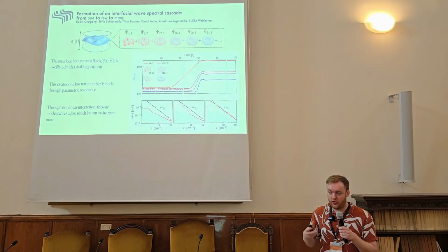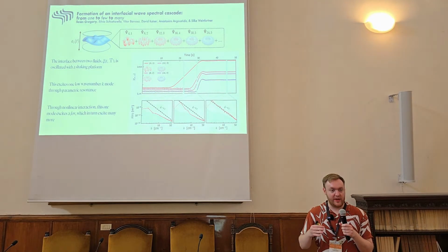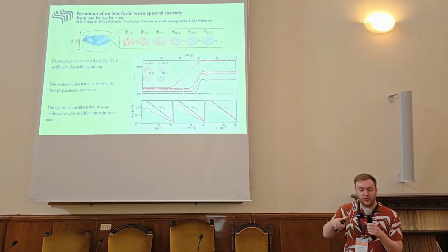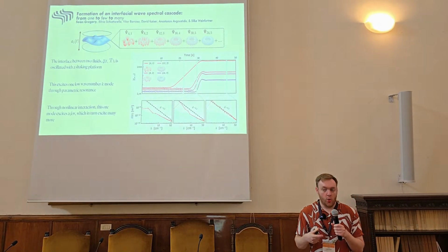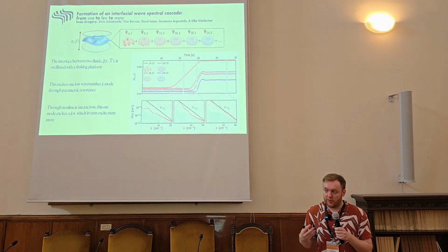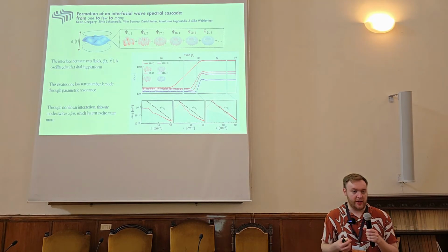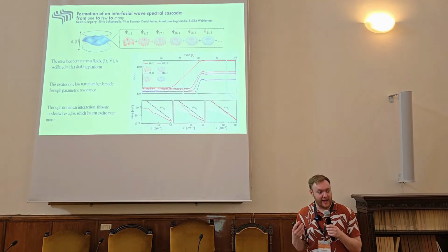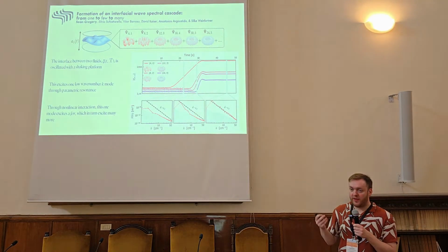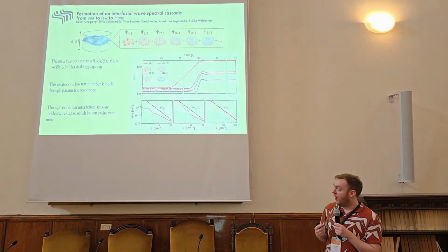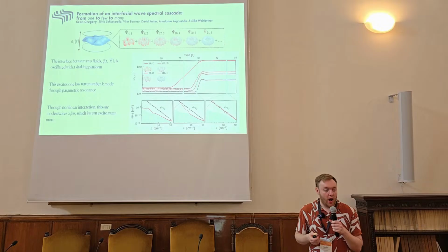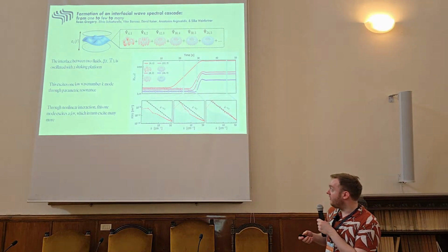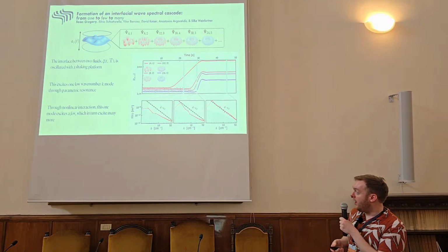We have two fluids that we fill a vessel with, and they separate out to form an interface between those two fluids. This vessel with the two fluids we mount to a bespoke shaking platform which provides a periodic forcing. Through a process known as parametric resonance, this excites one particular large length scale wave mode. Then through nonlinear interactions, the energy passes from this one wave mode to wave modes at larger wave numbers. And so we see in real time the build-up of what's called a direct energy cascade, which is characterized by a power law scaling behavior in the power spectral density.